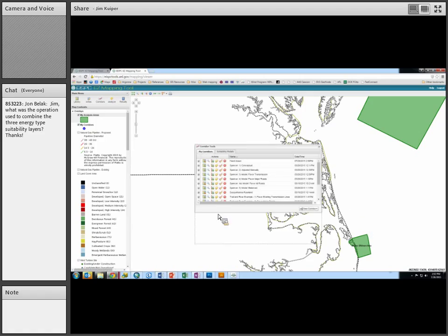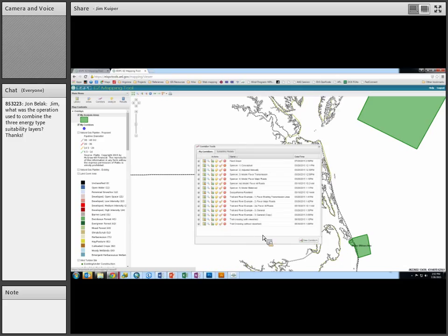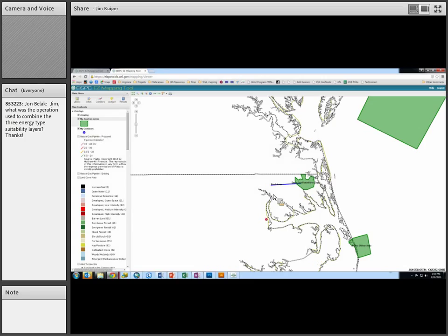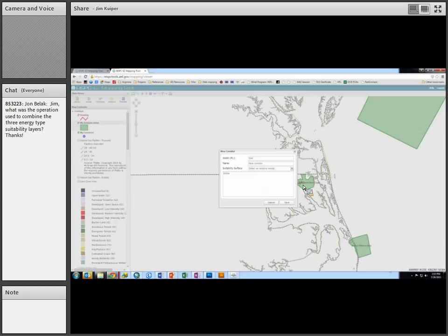Okay, so I've got a series. I've already created a lot of corridors, so I'm going to create another one. And if I generate from endpoints, we can use the same 2 points that we had originally. So here's a starting and an ending point. And I don't need to double click for points, just 2 clicks for the 2 endpoints. I can give it a name. It's called pipeline corridor.